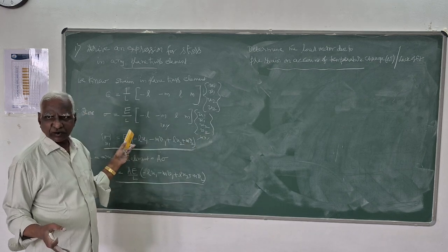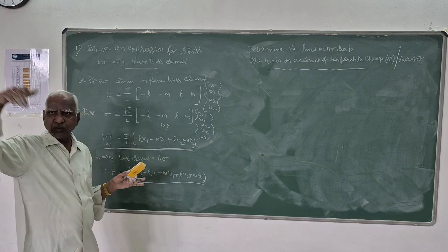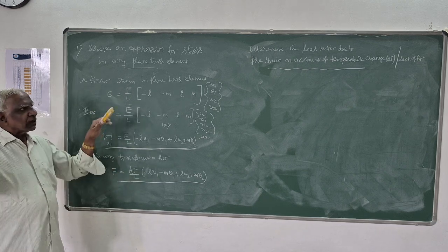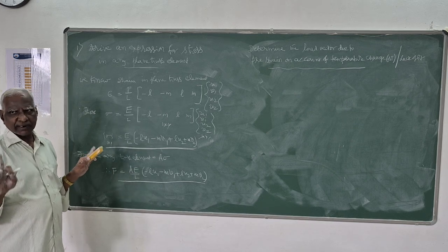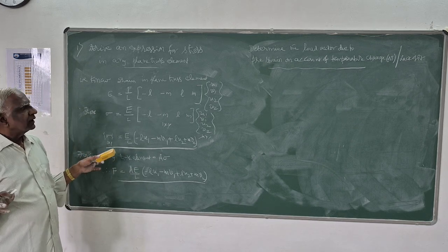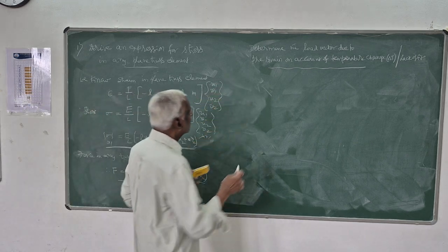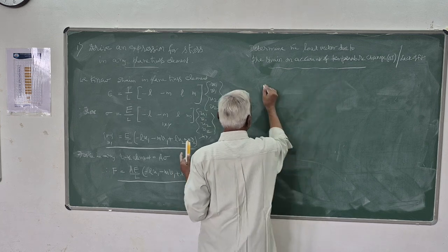Surface force is not coming into picture at all in trusses because the members are not subjected to member loading. So only joint load. So joint load, always you take upwards positive, downward negative. That you have to remember while solving the problem on displacements. So now we will give the expression for the temperature change.